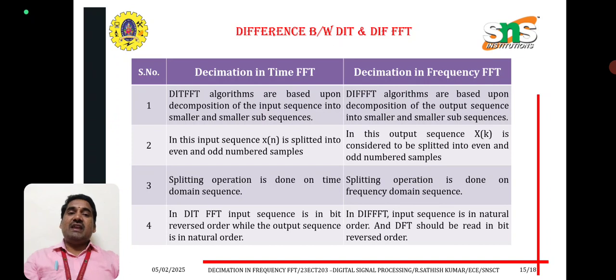In DIT, the input must be in bit reversed order and the output will be in normal order. In DIF, the input sequence is in normal order and the output sequence will be in bit reversed order.